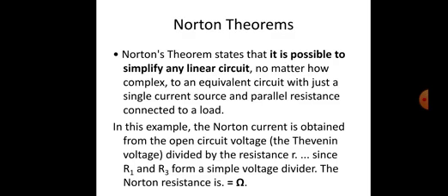As with Thevenin's theorem, everything in the original circuit except the load resistance has been reduced to an equivalent circuit that is simpler to analyze. Like Thevenin's theorem, the steps used in Norton's theorem to calculate the Norton source current and Norton resistance will be generally similar.